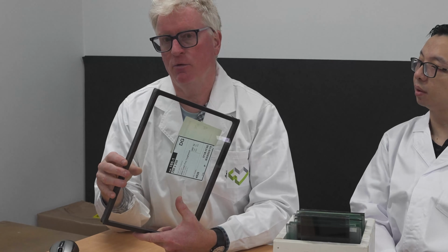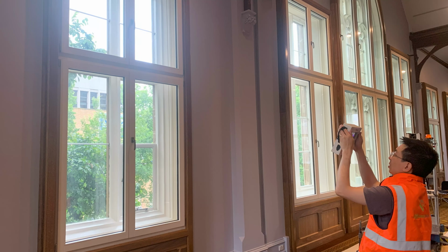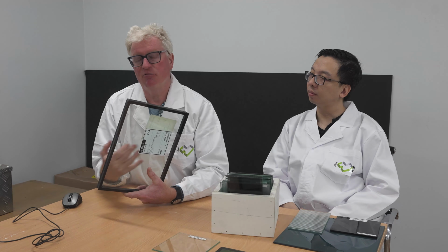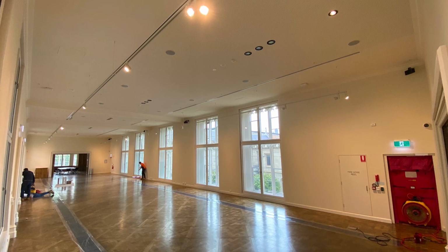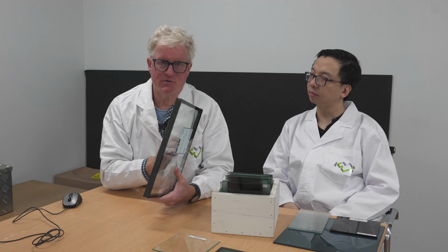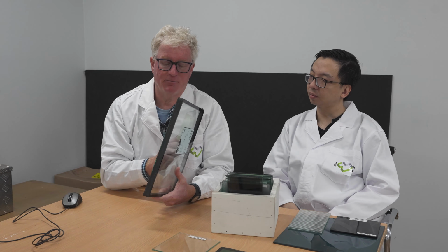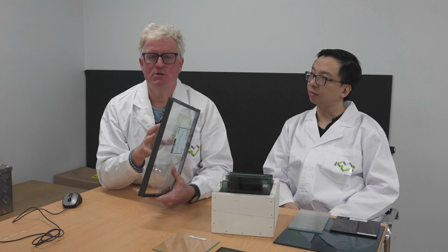The biggest breakthrough in history was the idea of sealing and developing a double and triple insulated glass unit. The glass itself, the properties don't change, but the composition of putting it together with various thicknesses of air gap and filling those cavities later with different gas types such as argon or krypton make the performance of a glazing system superior to what it was 50, 60 years ago.